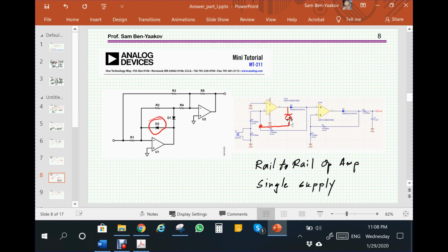I'm going to show later on that you can have an offset that will then allow the use of a diode. Now, you can then subtract this offset by the microcontroller that is reading the A to D, because this is going to be read by a digital controller, and therefore everything will be positive, but will be riding on a certain offset, and this offset can be then subtracted, and it will allow to put the diode. So I'm going to show it in my next video on the subject.